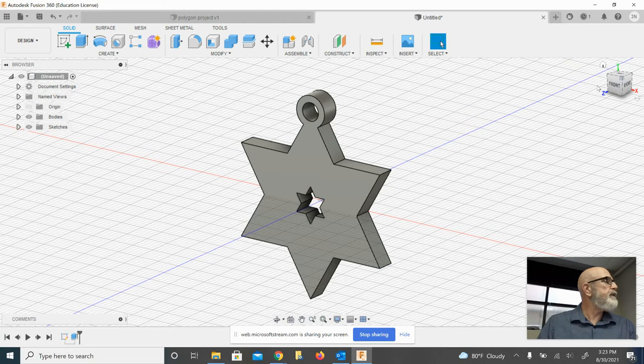And let me get to that section in the tutorial. All right, so we are going to draw a circle of 16 millimeters that we're going to pattern on the front of this. Then we're going to put cylinders in a circular pattern around that correspond with each point of the stars. Okay, and in between them, that'll correspond with these inner areas, we'll put a sphere in place.